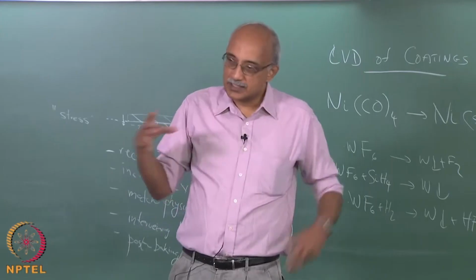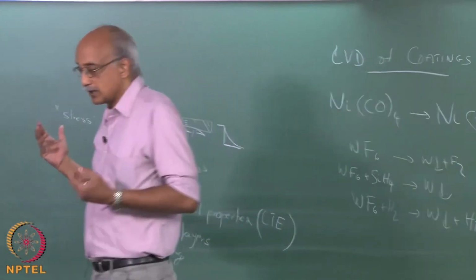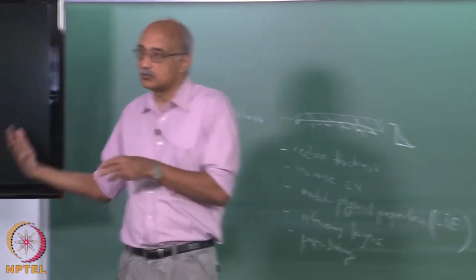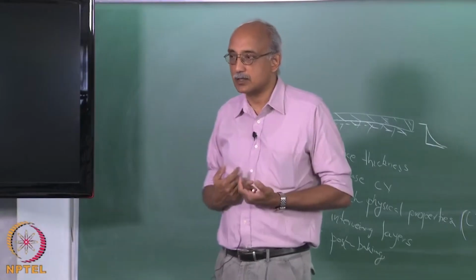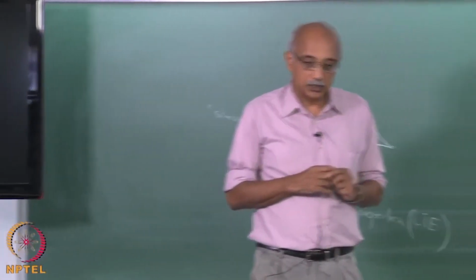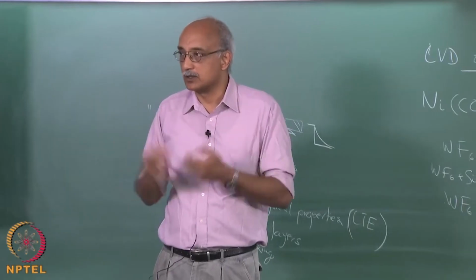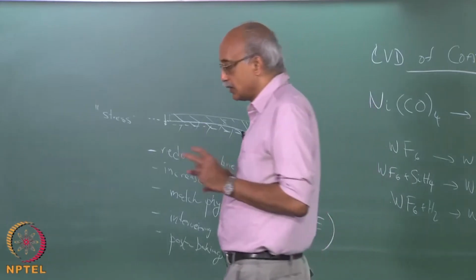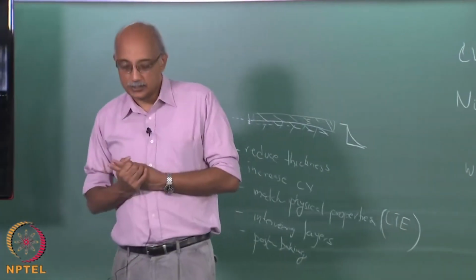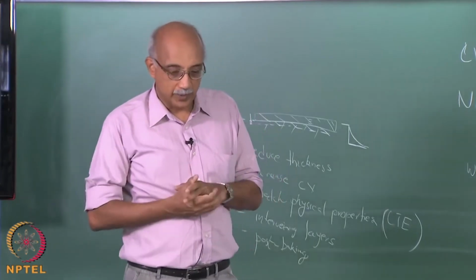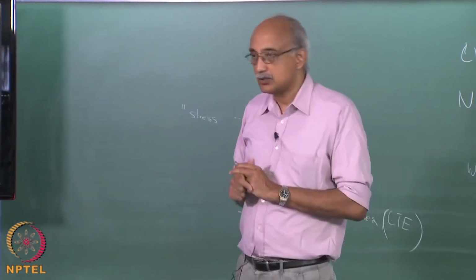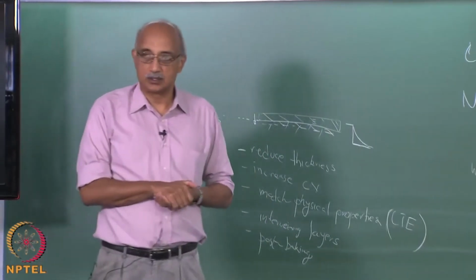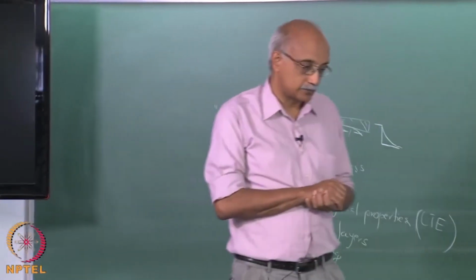So, everything is happening inside a vessel. Unlike the classical CVD process where the preparation of the precursor happens outside the CVD reactor and then you feed the precursors into the CVD reactor where the coating takes place, here everything takes place in one reactor, so to speak. You are generating the vapors in situ, and you control the transport phenomena inside this reactor in such a way that the reactive vapor species that are formed are directed to flow over the substrate that you are trying to coat, and the film deposition happens within the reactor itself.